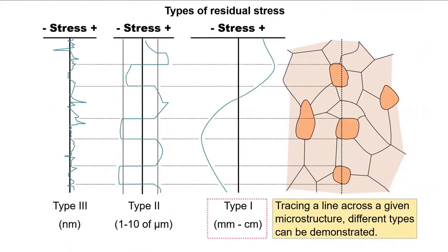There are three types of residual stress. The most prevalent ones you will likely encounter is type 1. These are continuum scale residual stresses which equilibrate over millimeters to even meters. However, there are another two types below this. Type 2, which equilibrate at the grain level for polycrystals. These are driven by texture, segregation, solid solution effects, amongst others.